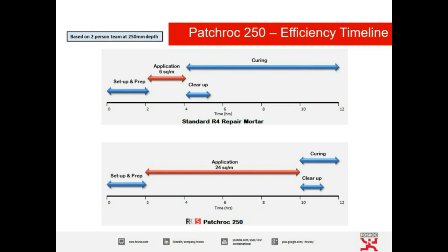However, if we look at the table below, you can clearly see that yes, we have our 2 hours preparation, but we're able to apply 24 square metres at 250mm deep with a curing period of just 2 hours. So the efficiency timeline there is a huge amount of improvement on top of what would be a traditional repair.